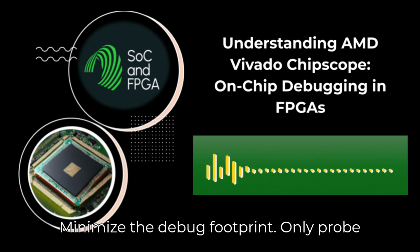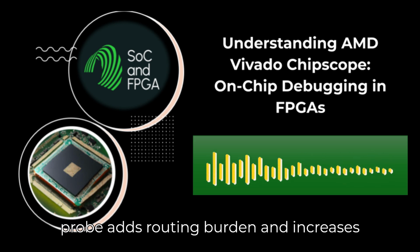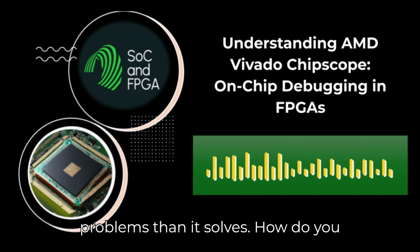Sometimes necessary, and critically, perhaps the simplest thing: minimize the debug footprint. Only probe the signals you absolutely need for the current problem. Every single additional probe adds routing burden and increases risk. Be selective. Don't just probe everything just in case. Please don't. It's tempting, but it often causes more problems than it solves.